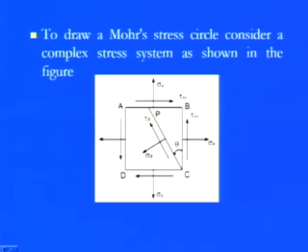At AB as well as CD, we have the shear stress component tau xy which is parallel to the plane. To counterbalance those shear stresses, we have tau xy, which is known as the complementary shear stress. So we have both components at AD as well as CB.